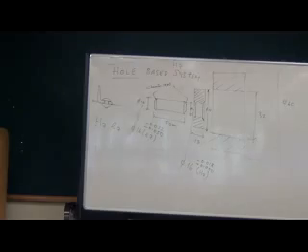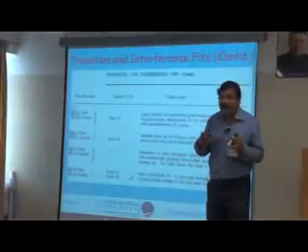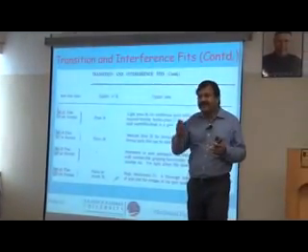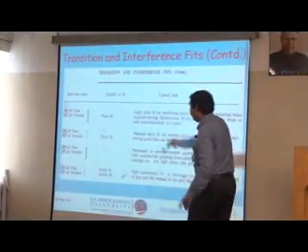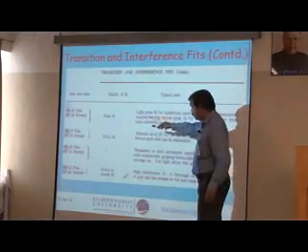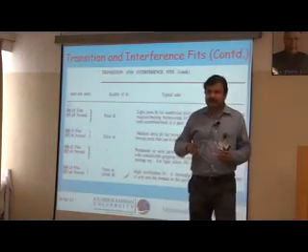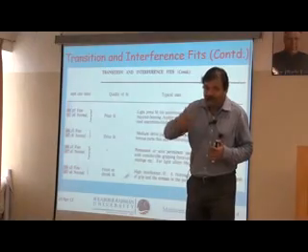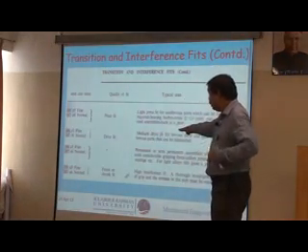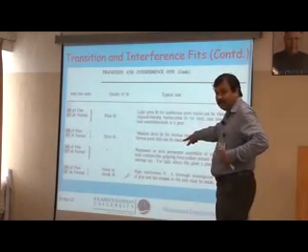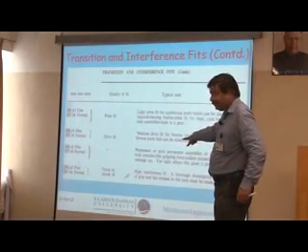So in the interference fit, I have to now decide how I want my interference. Is it just good enough if I just press it with some force? That is called a press fit. Then drive fit. It is more of force. You understand? I have to drive it. Still heavier driving. Then what is the next one? Force or shrink fit.